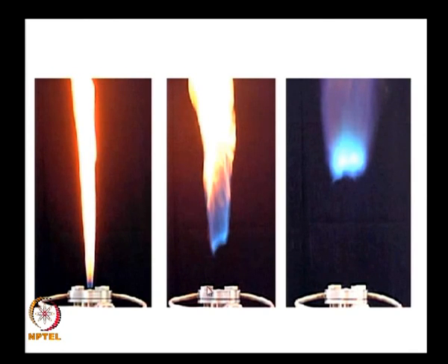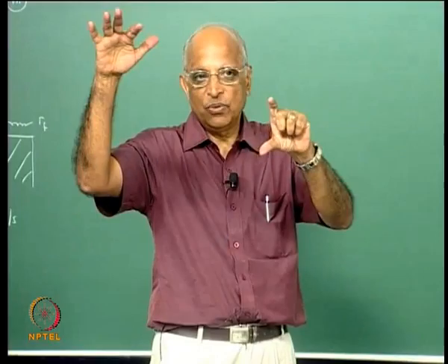I have mixing taking place in this zone, and thereafter I have combustion, and still at a higher velocity. Well, this zone is the zone wherein mixing is taking place, it is at high velocity, the heat is insufficient to propagate the flame into this. I have something like a standoff distance here. Well, the standoff distance is something on these lines, but not precisely because of velocity, but it takes a certain distance for the final diffusion flame to form.